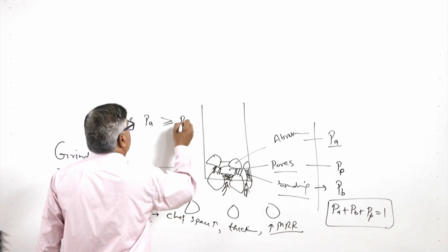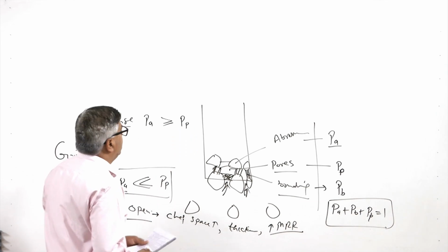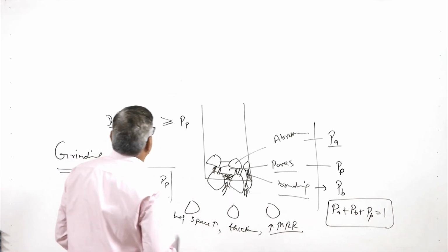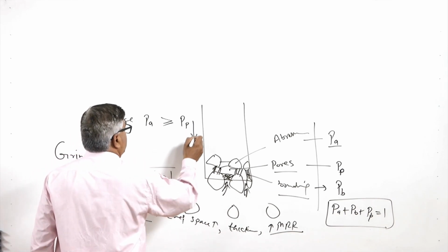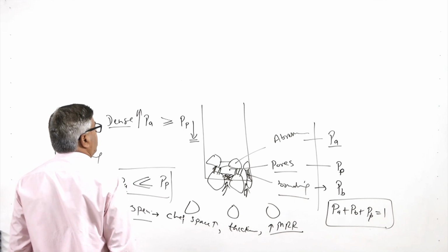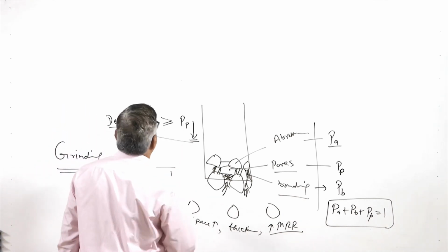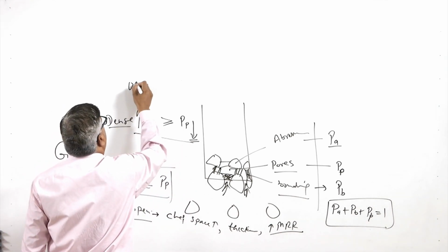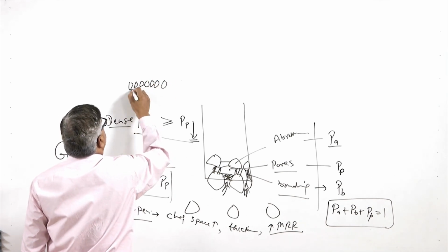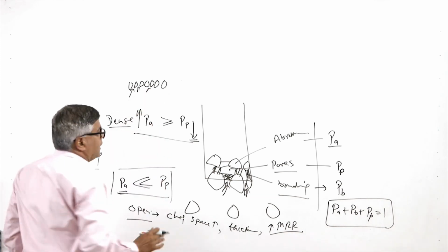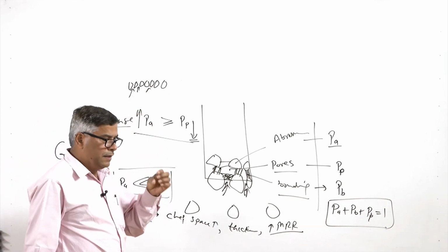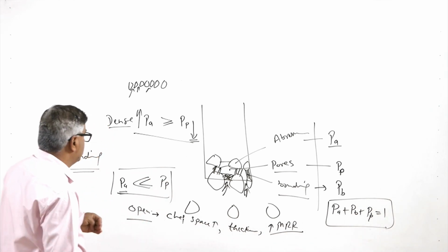and the fraction of pores is less. A lower percentage of pores and a higher percentage of abrasives will lead to very closely packed abrasives. In this case, very little chip space will be present between the abrasives, which limits the removal of larger amounts of material during grinding.